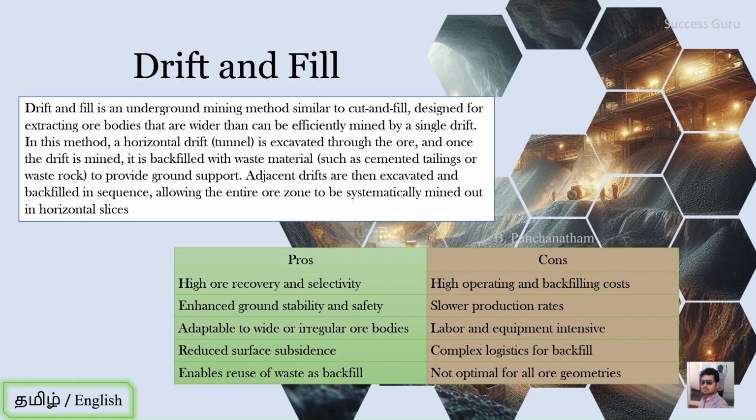When you are going for mining, whether it is open cast mining or underground mining, there is a very big problem with the overburden or the country rock breaking, right? We have to dump it somewhere on the surface. To counter that, they are using that waste as a refill. So that problem is also reduced in this type of drift and fill method. So these are the advantages.